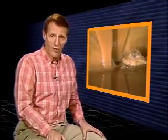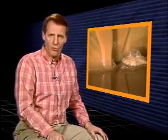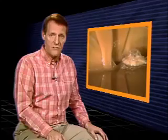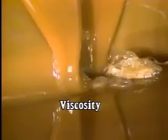Oil is a liquid lubricant made from a synthetic substance or from petroleum. Oils made from petroleum are natural lubricants. Natural lubricants are the types most widely used in industry. One characteristic of oil is its viscosity. Viscosity is a measure of a liquid's resistance to flow and is an important consideration for determining the suitability of an oil for a particular application.